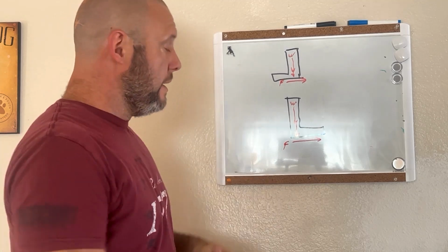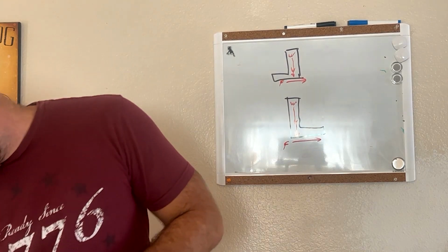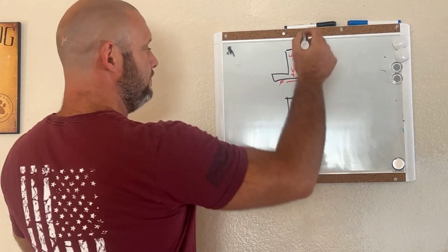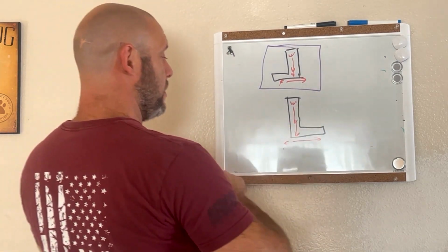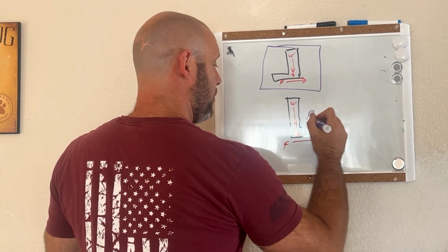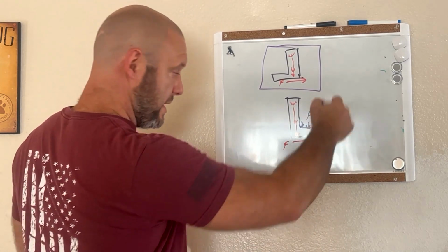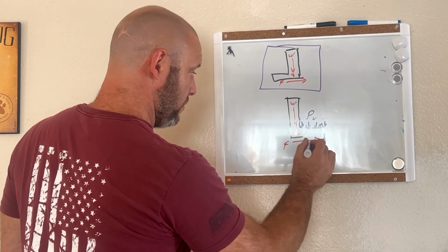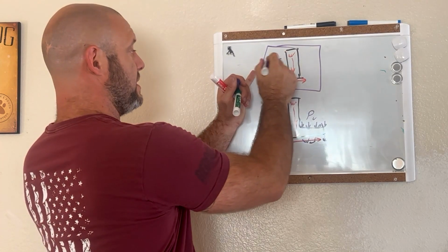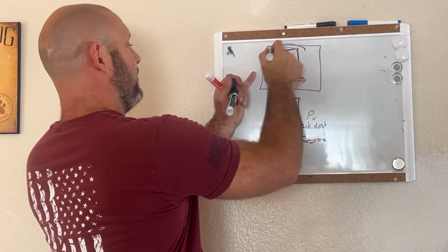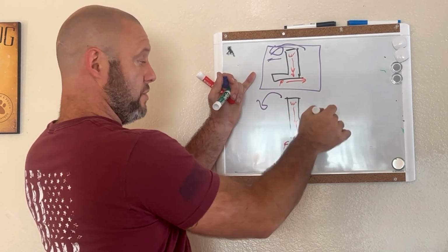So why does the L shape that points into the hillside resist better than one that points away from the hillside? The reason is, when you put the soil in there, instead of just having these forces as my resisting forces, when you pop the soil on, you also have passive pressures pushing down on this wall. That weight translates to further weight down into the soil, right? And by pushing down on something that's connected on the L shape, much like this, it resists the overturning, right?